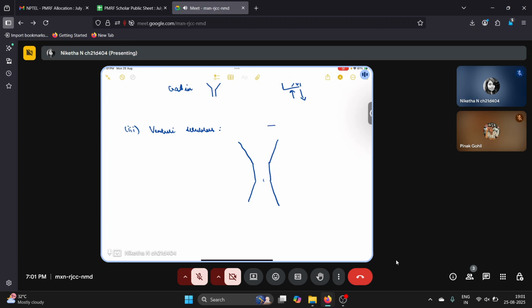So here the gas comes in here, and then we have the liquid inlet from here. The liquid enters just before the throat section. Because the area here is quite narrow, the velocity will be quite high, so there is acceleration of the water particles.